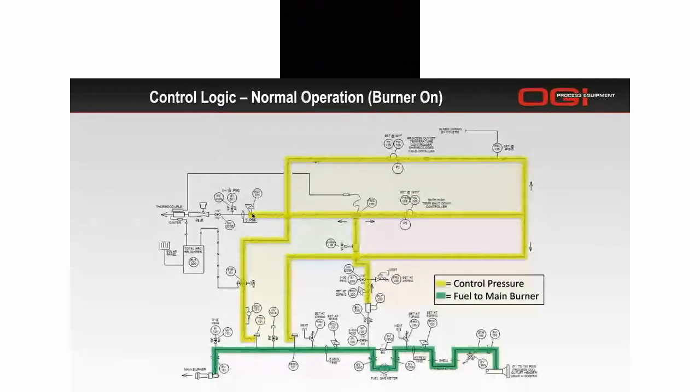We are feeding the pilot system, and we're also holding open our temperature control valve and shutdown valves. When these valves see pressure at their sensing point, they're going to open. When they don't see pressure, they're going to close. It's known as a fail closed valve.